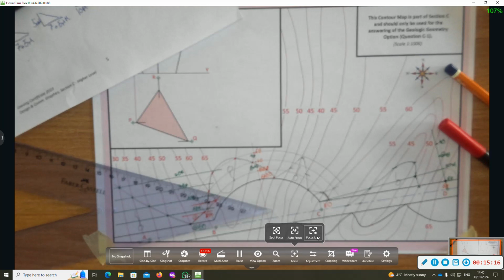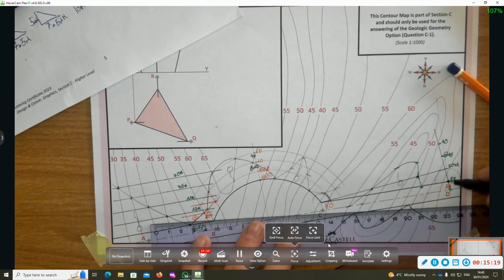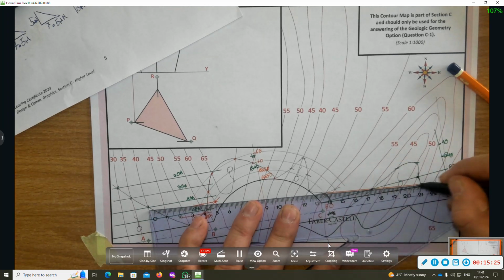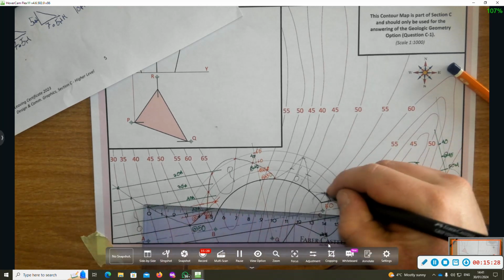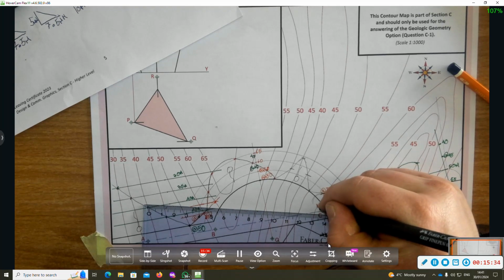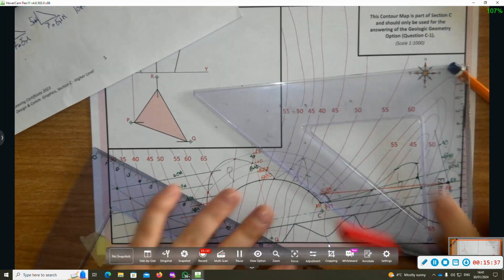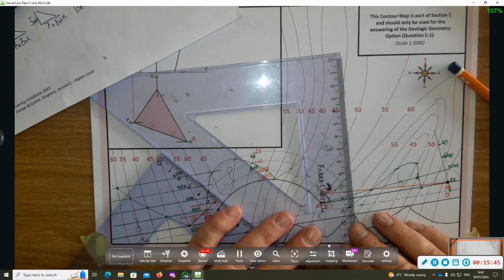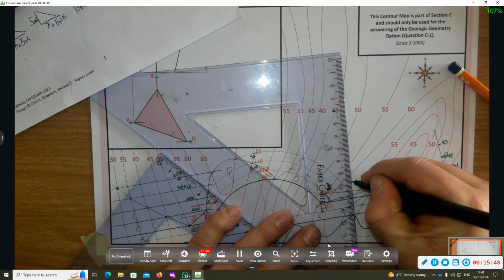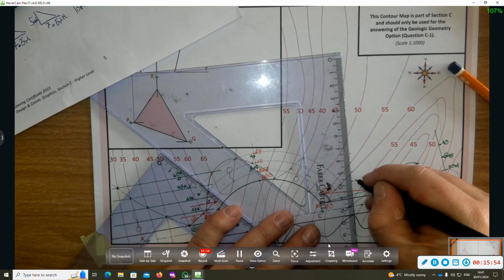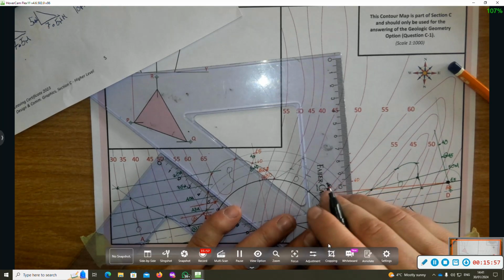Now, we're going to join our 55 as a tangent to the circle. So that's at altitude 55, the base. Center point is at 50. And we're going to go perpendicular to that. Marking up every 7.5. So that's at 60, 65, no need to do any more.